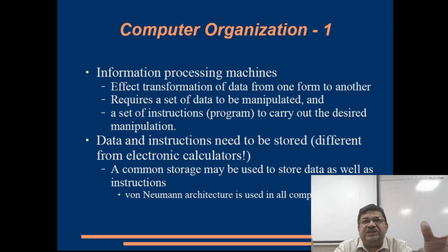Those are a discrete set of numbers, and there are certain values in between which are not available, and anything in between is just void. Nothing is known. So there is something called quantization error, and no matter how large a word length I take, there will always be some quantization. Whereas for analog computers, it's a continuous flow, a continuous waveform, and it is all in full precision.